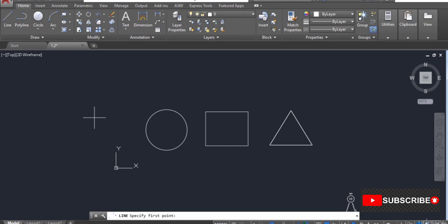Simply go to that command and left click, and the command will now be activated. Once the command is active, you'll notice that its name and also the instruction will be visible on the command line, and the cursor will change into a point selection cursor or a pick box. In order to exit this, simply press the escape key. You can press escape multiple times if you want, so that will not make any change to the drawing.